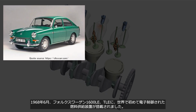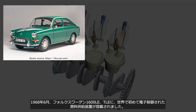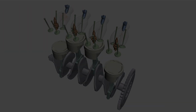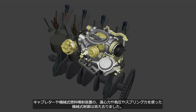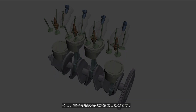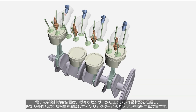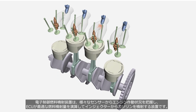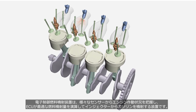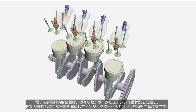In June 1968, the Volkswagen 1600 LE and TLE were equipped with the world's first electronically controlled fuel injection system. The days of mechanical controlling using centrifugal force, vacuum, and spring force in carburetors or mechanical fuel injection systems had come to an end. Yes, the era of electronic control had begun. The electronic control fuel injection system is a device that monitors the engine operating conditions from various sensors and calculates the optimal fuel injection quantity through the ECU, engine control unit, to inject gasoline from the injectors.